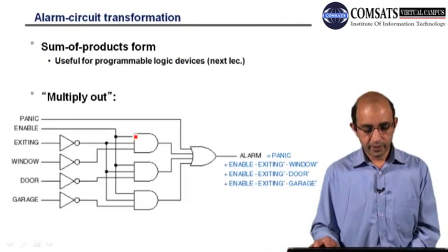You can see that we have an AND gate over here that represents the product, and we are performing the AND operation between enable, then exit, and it's in complement, and then window also complemented.